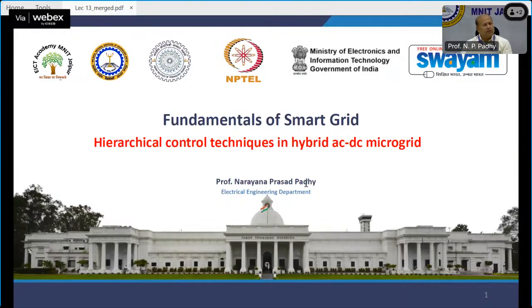There are many devices. Today, if I ask you what the components of an AC/DC microgrid are, we'll start with AC load and DC load. Then we move to AC generation, such as the main grid and wind generation. We will also talk a bit about diesel generators, which are connected today, though we do not want to have them. And then you go to DC generation like PV and batteries.